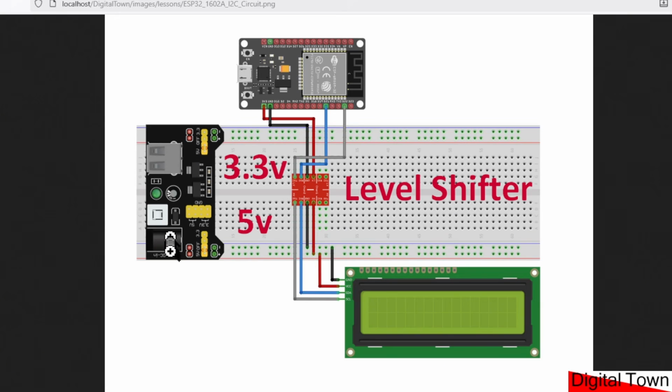Now, this is coming from this external power supply. Technically, you could possibly use the VIN pin if you're supplying your ESP32 with 5 volts. But the way I tend to work on a project is the board will be receiving 5 volts from somewhere, so I will tend to take the same power supply that will be going to my project and send that to the screen. However, because in these examples I'm using my USB supply, I'm going to be using a separate power supply for the LCD display, and it's a good habit to get into.